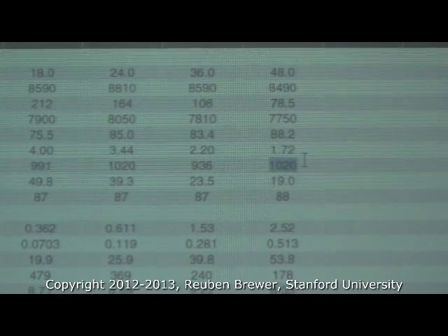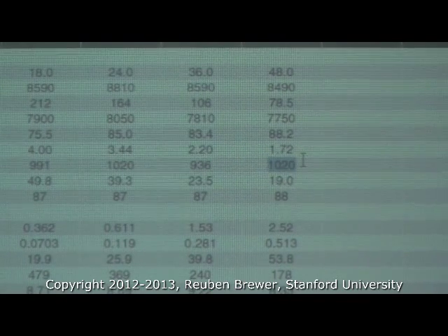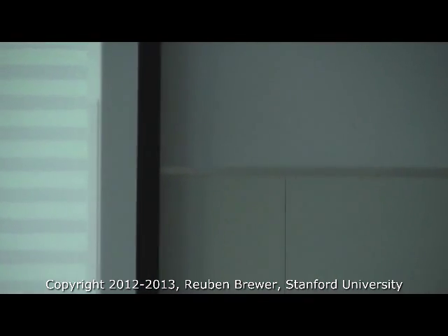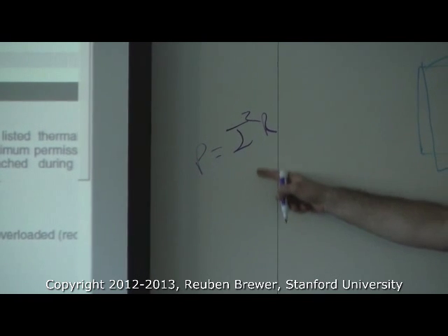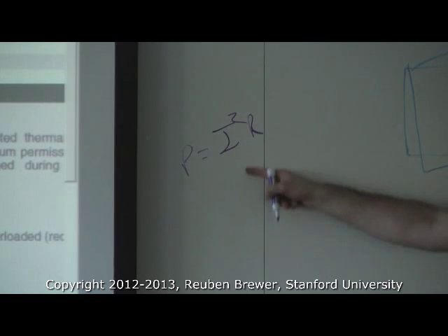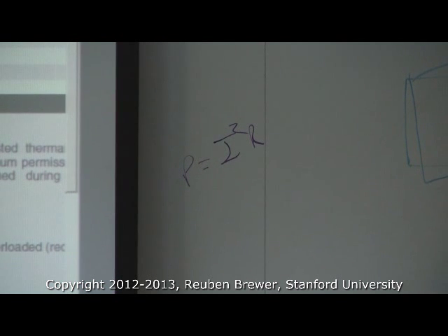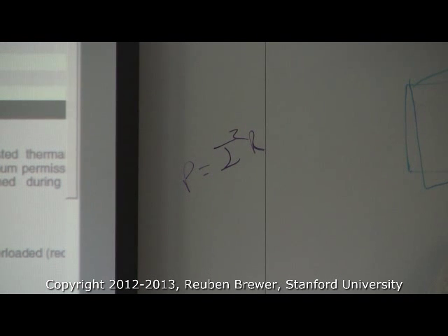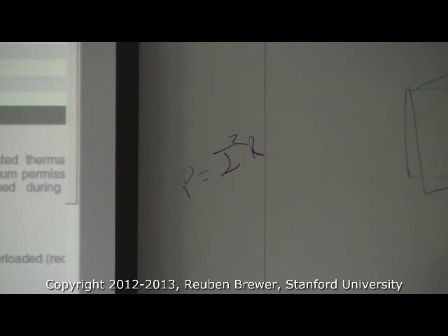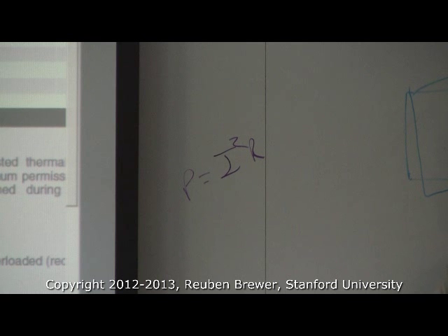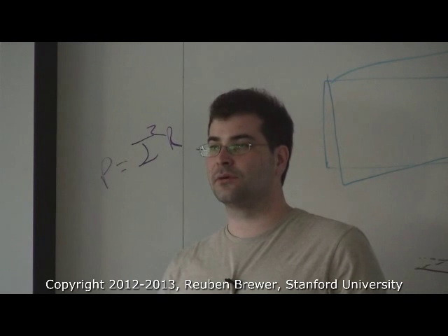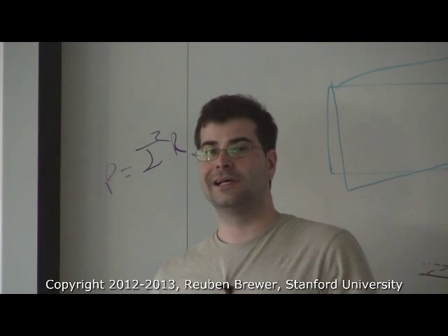So basically, the resistive loss I squared R in the coils is the power we lose from the current. This is squared, right? So as current goes up a little bit, the power loss goes up quadratically. And what that heat is doing is breaking down the insulation between the individual coils of wire in the rotor. Eventually it's going to melt something in there, which is going to get in the bearing so it will cease to spin, or it will just short across the loops of wire and then fry your motor.